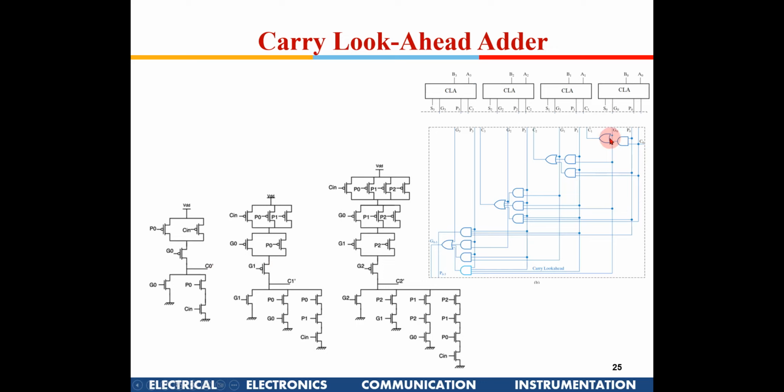These two gates have been combined by this circuit, and together they will bring in only 2 gate delays. So that is the advantage. That is the reason why we didn't stress that this is an OR and this is an AND. We just considered this as AND, because in combination these two together will introduce 2 gate delays only.